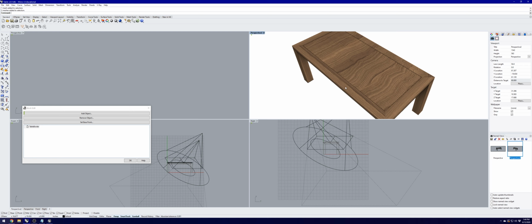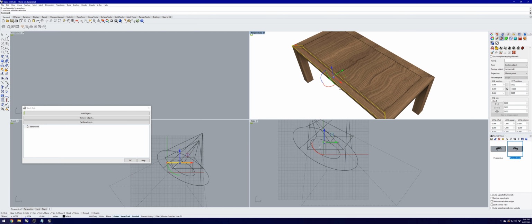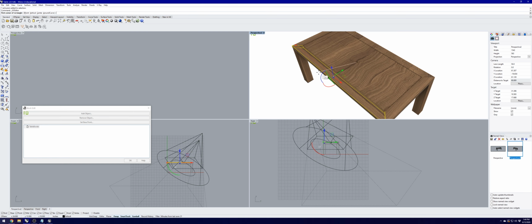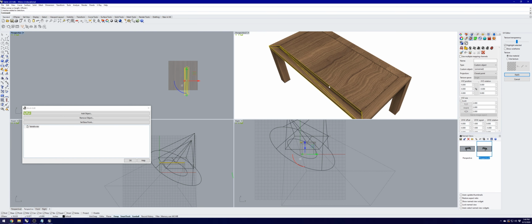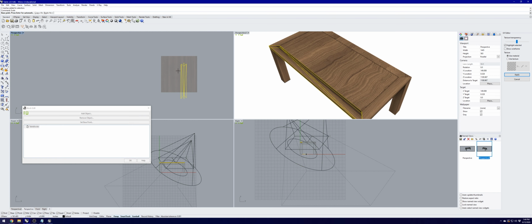One thing I do want to mention too with UV mapping is if I click on my geometry and I open back up that UV map, if the scale of this UV map is not the size that you want it, you can type in scale over on the left hand side after you've selected your UV map, and you can change your scale. So I just single clicked and say I wanted my texture to be twice as small.